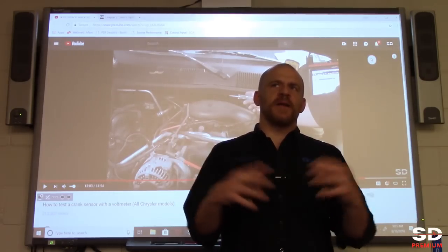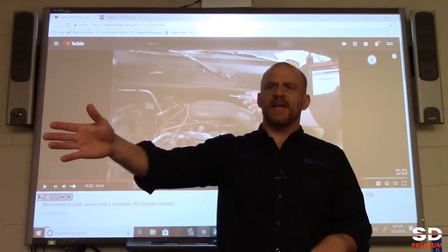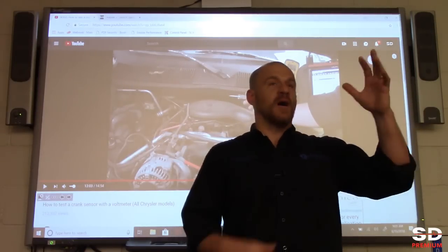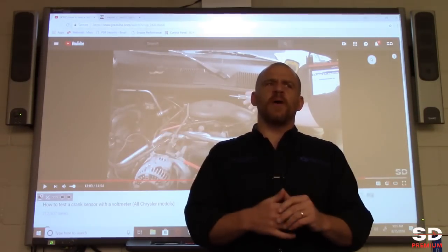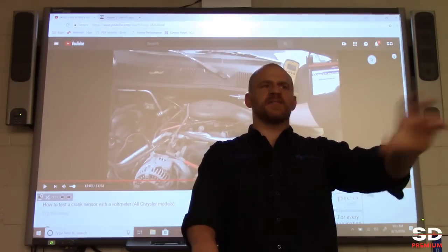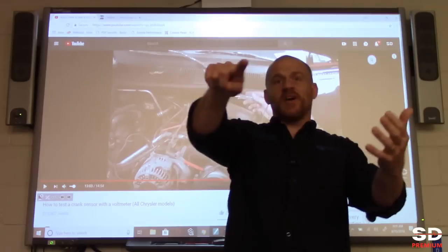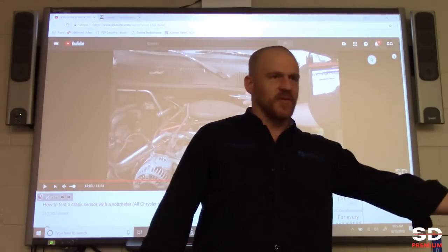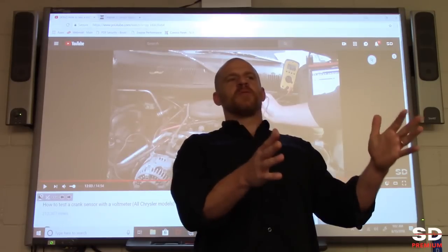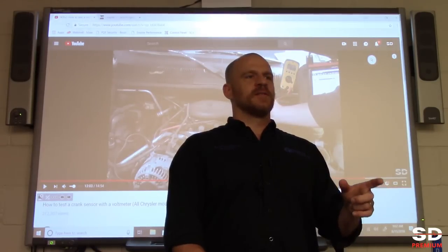So the comment was about an AC system problem and using a data parameter where you select AC and then you see on the scan tool it says yes, but the AC clutch still isn't coming on. A little bit different scenario than what we're talking about, but yes, you will still see that command, and that command doesn't tell you that the clutch is actually on. Even if it says AC clutch yes, and then you go under the hood and there's no power going to the clutch, you have to remember that you're looking at what the computer wants, not necessarily what the computer is getting.